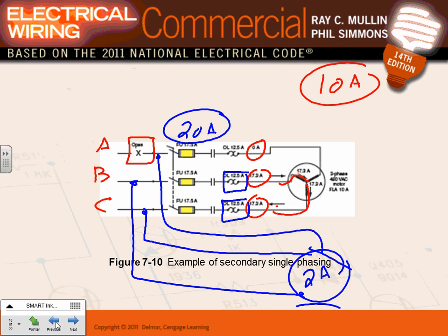If you have a single phase condition, the second motor, the smaller motors will continue to run, and the bigger motor will generate equivalent to the loss of the phase. I don't want to get even deeper on that one. That's confusing for the maintenance electrician and engineers, guys. You walk in and you measure the phase and it looks like there's a voltage in it, but that voltage is generated by this motor into this motor, even though we lost phase A, but we still have voltage and running other motors.